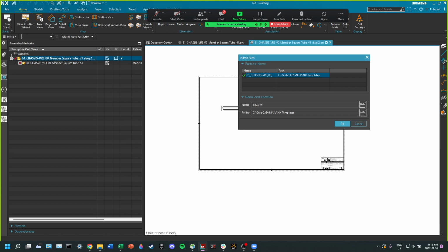But before you start your number, you're going to put a lowercase d in front of that, and then do your A2001 or 3005 or whatever, and then your description, tube, and then put drawing after it, so that we can see that it's the drawing. Then just save that in the exact same folder that your part CAD is saved in.